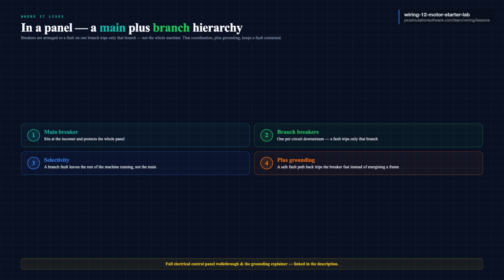The other half is grounding, so a fault current has a safe path back and trips the breaker fast instead of energizing a frame. I have a full walkthrough of an electrical control panel and a separate video on grounding, both linked below.